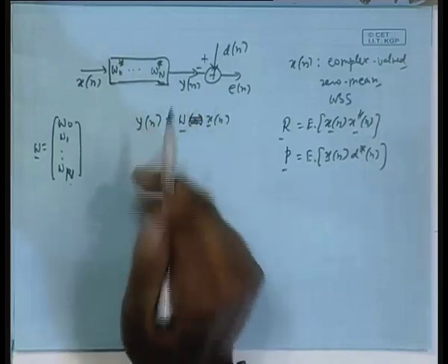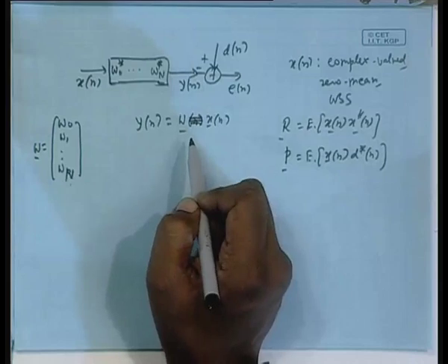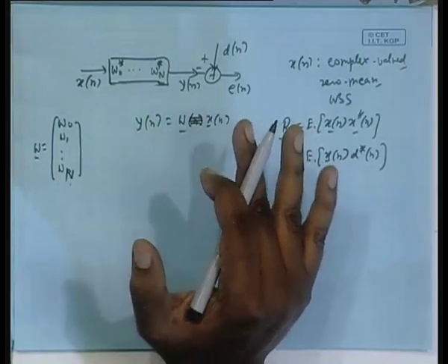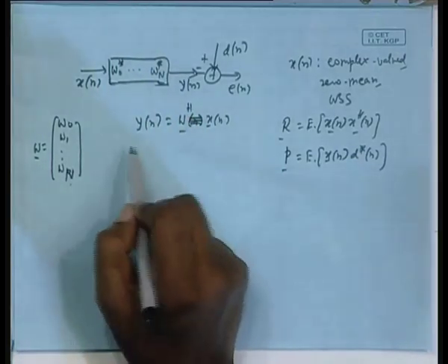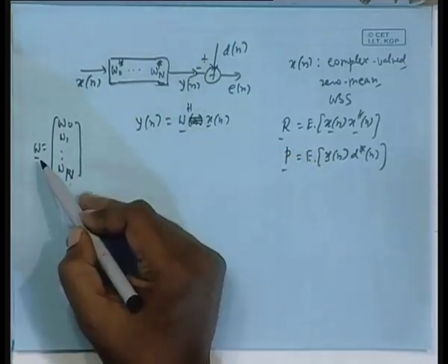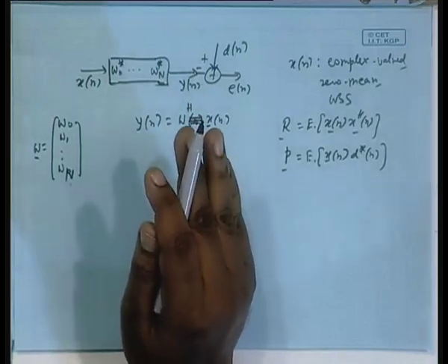Only when it becomes adaptive, then I bring in the index n and all that. So, to start with, it is not adaptive, I am just trying to find out the optimal set. This is an optimal Wiener filter. So, some W I start with and W Hermitian. So, Yn is W Hermitian Xn, no problem, because this is my W and I said in the filter there will be star. This is just a notation, nothing else.